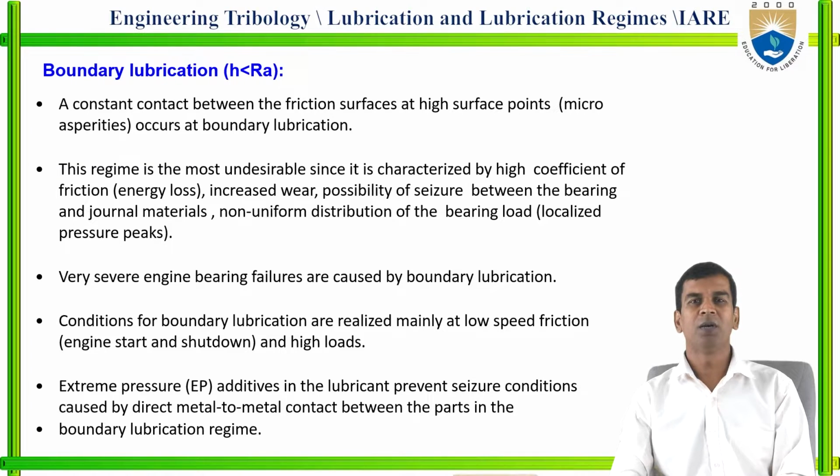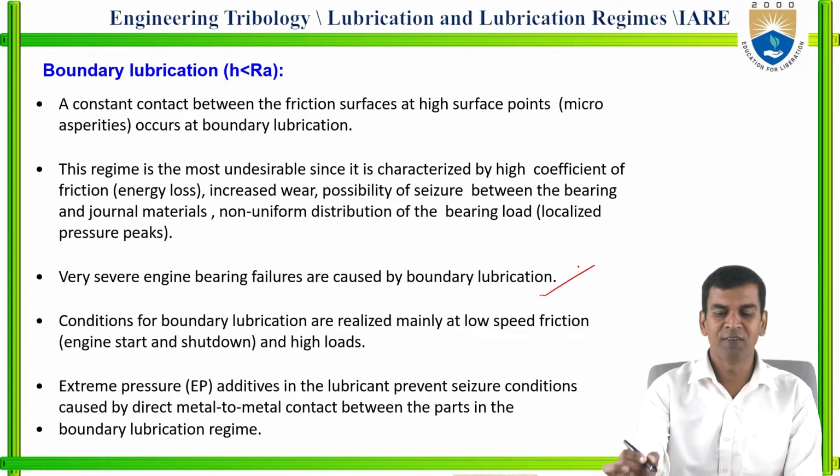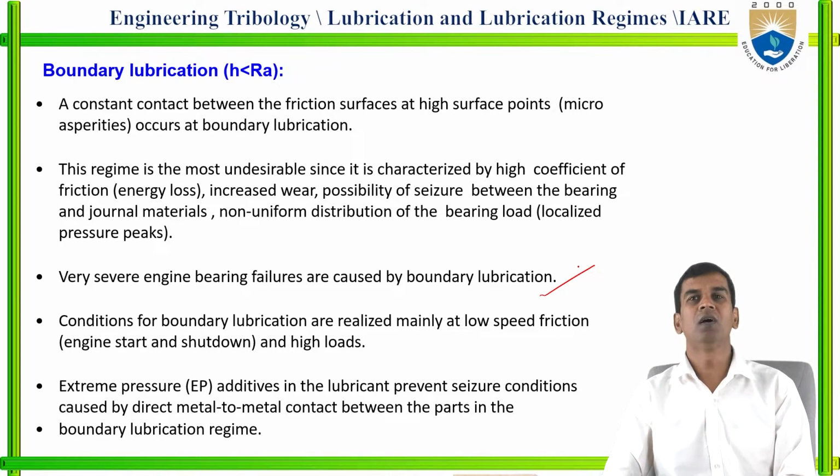This boundary lubrication regime is undesirable because it has a high coefficient of friction, increased wear, possible seizure between the bearing and journal materials, and non-uniform distribution of load. Very severe engine bearing failures can be caused by boundary lubrication.